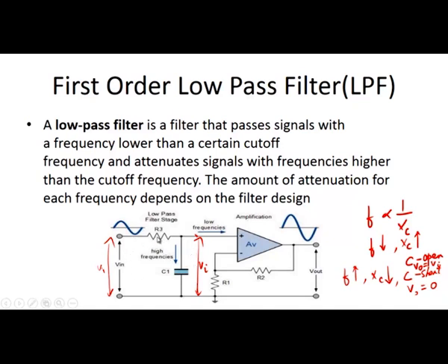Always, when the frequency is related to the capacitor, we have to remember this: the frequency is inversely proportional to the capacitive reactance. If the capacitive reactance is very high, the capacitor in the circuit is treated as an open circuit, and if the frequency is high, the capacitive reactance is low, and the capacitor is treated as a short circuit. The remaining things we have discussed now.